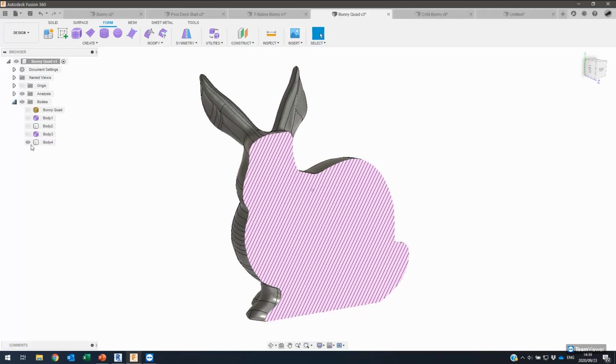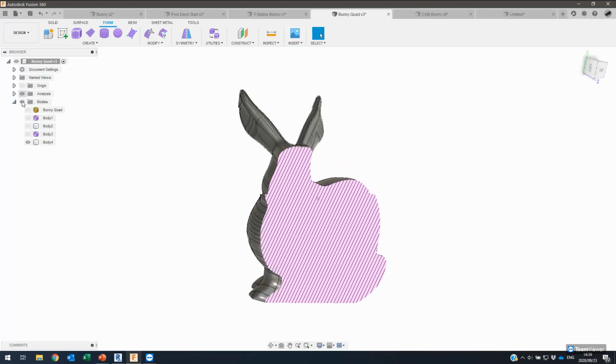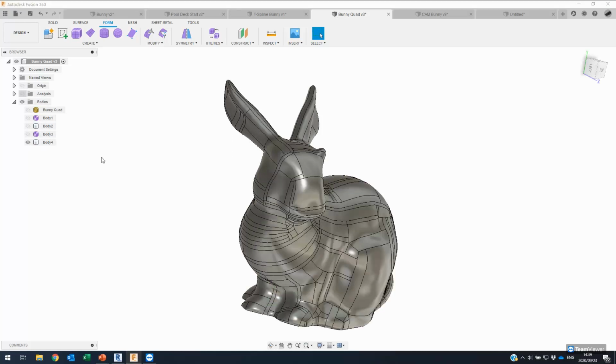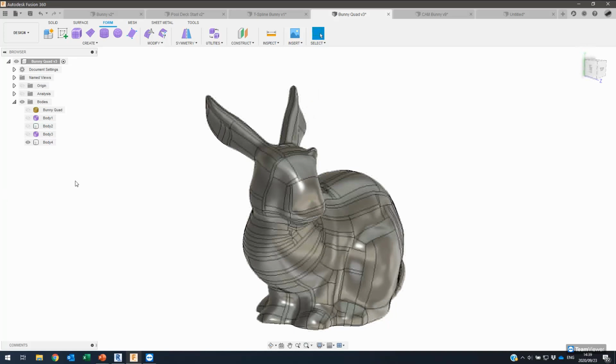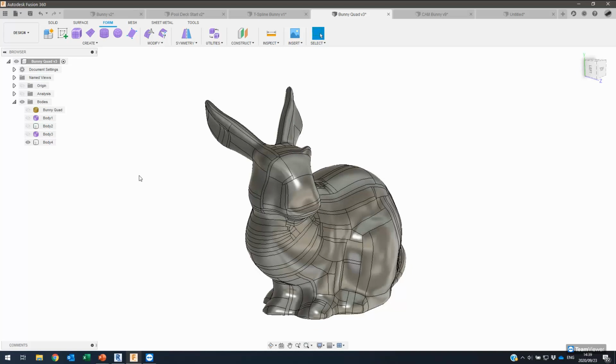So that now gives you something that you can continue to model with, you know, converted from your scan data through to a quad OBJ, and essentially throughout the process getting you a solid model. So you can use those existing meshes to create that new geometry. So various ways there, either converting the mesh or using T-splines to match up to the mesh.